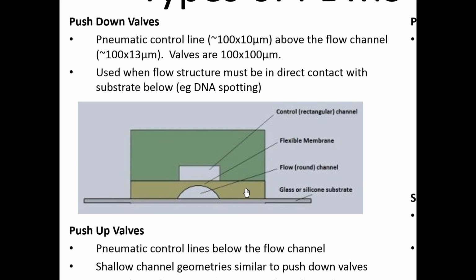Then you have a second layer of PDMS, and this is the thin layer, shown in sort of the gold color. Now, this is also done with an SU8 layer. However, the thickness of the PDMS layer is only maybe 50 to 100 microns thicker than the SU8 around it. So what you'll end up getting is a pattern that will be rectangular initially. It won't be circular unless you reflow the photoresist. The photoresist pattern will initially be a rectangle, right?